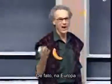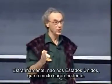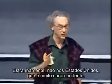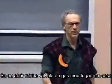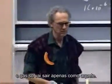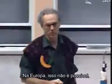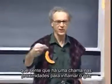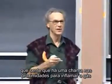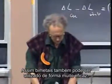In fact, in Europe, all gas stoves are protected that way by law. Strangely enough, not in the United States, which is very surprising. If I open my gas valves at home of my stove, the gas will just come out. Just like that. There's no prevention of that happening. In Europe, that's not possible. There's always a pilot light somewhere with a bimetal that senses that there is a flame nearby to ignite the gas. And if that flame is out, the gas valve will be closed. So bimetals can also be used very effectively for safety devices.